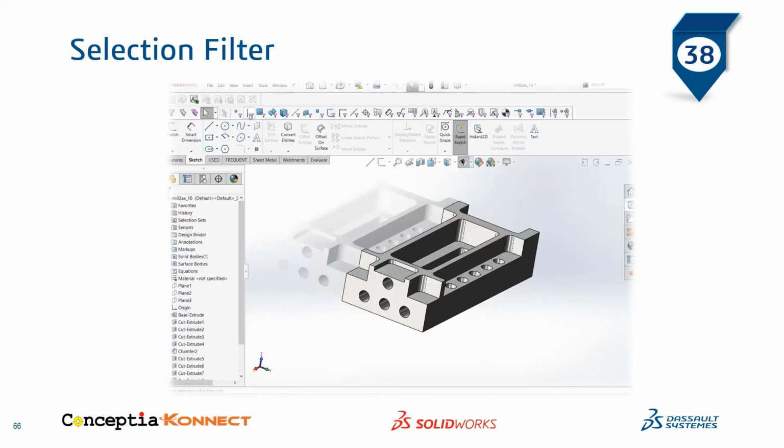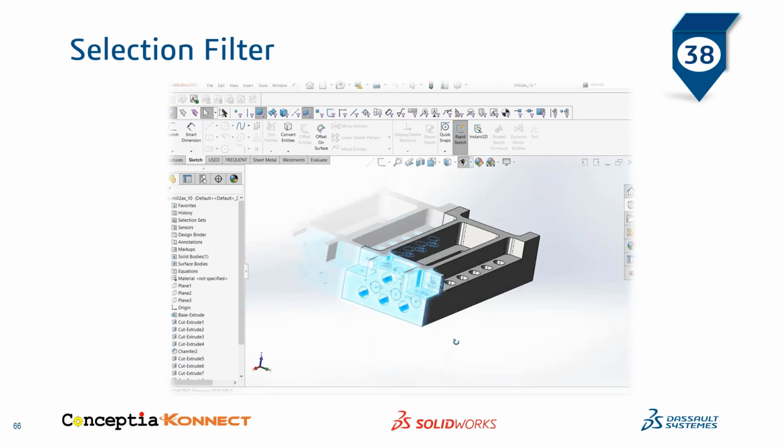So in the selection filter I will select the edges. Only the edges are selected. Even if you select a face, it won't be selected. Now face filter, all the faces are selected.